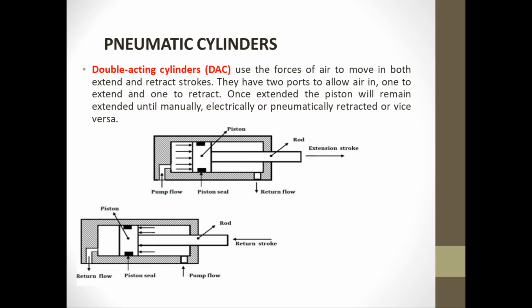So unlike the single acting cylinder that uses a spring, the double acting cylinder uses air pressure both to extend and to retract.